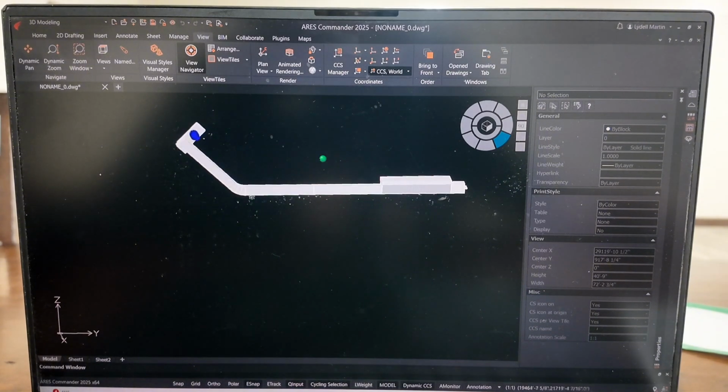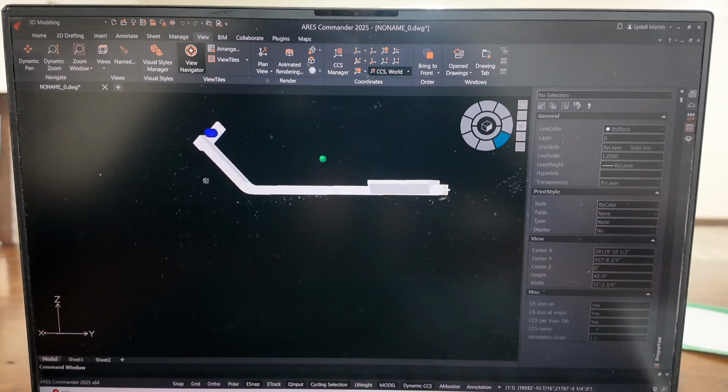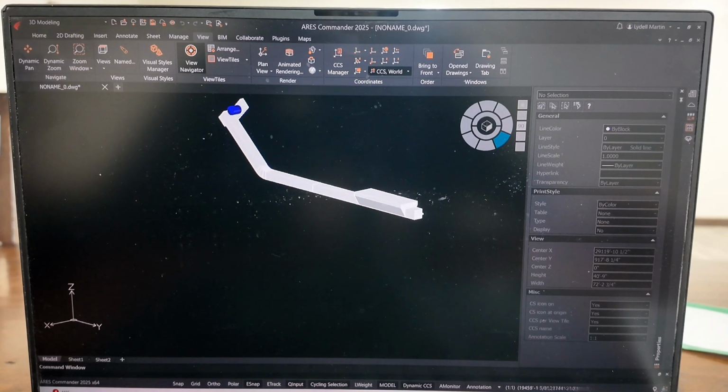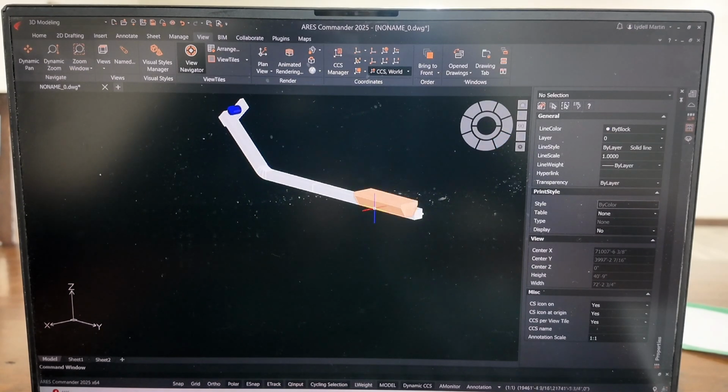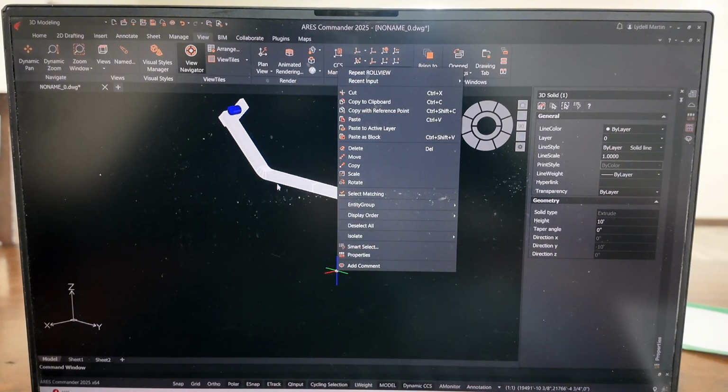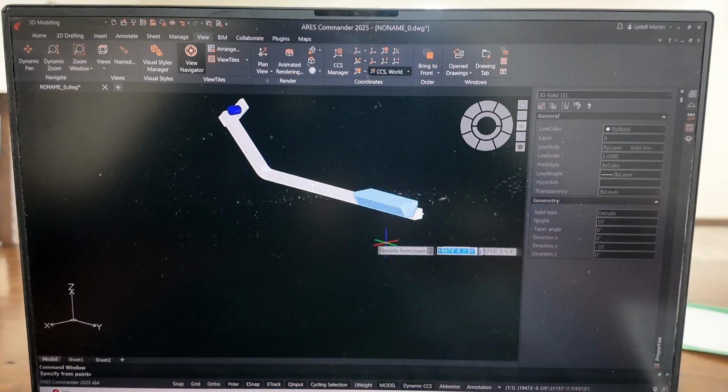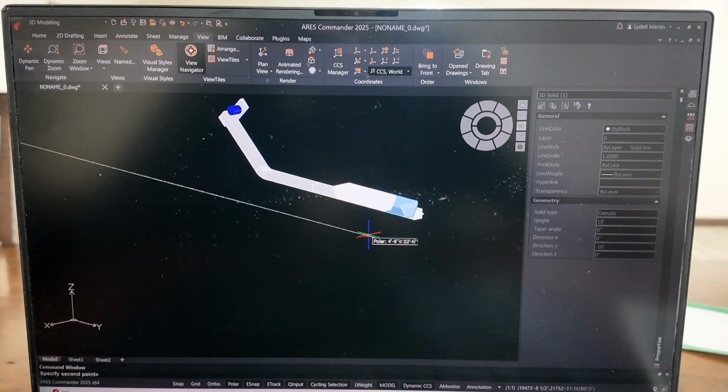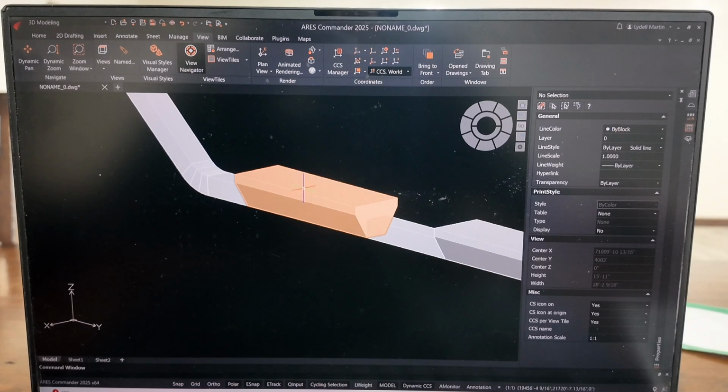Receiving drag. You can make this same pit if you said, okay, escape. We're going to select this pit because we wanted another little pit in here. So we're going to hit copy. We're going to move this over. No. We're going to move this down here to here because let's say a hopper bin's going to be setting over it here.